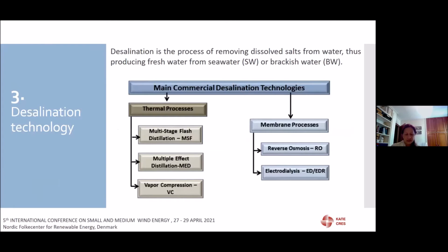Water desalination has become a technologically and economically viable solution to tackle the challenges associated with increasing water shortages. Speaking of commercialized desalination technologies, they categorize into two main subgroups: the thermal processes, in which we have multi-stage flash, multi-effect distillation and vapor compression, and the membrane processes. Here we have reverse osmosis and electrodialysis.